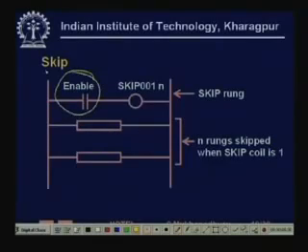You can have various other functions, like bit manipulation functions, and various kinds of block moves, etc. You also have various kinds of logical instructions. Apart from data transfer, the last instructions, which are very important, are program control instructions, by which we want to control. We don't want to execute all rungs of the RLL at all times, but rather we want to control whether we can skip some of them or enforce some of their values. To give an example, we have a skipping facility. When this skip 001, a very special type of contact, is enabled, it means that the next n rungs are skipped, where n is a parameter.